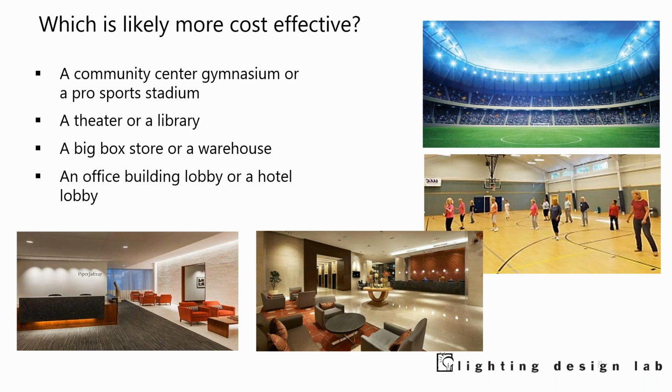If we look at the lower one, we've got an office lobby and a hotel lobby, and maybe they both have the same power density, the same lighting loads, but guess what? That hotel lobby is 24/7. It's open all day, all the time. Whereas the office, they may be open at 7 in the morning at the earliest, and then they close by 7 in the evening. So you've got to look at those hours of operation.